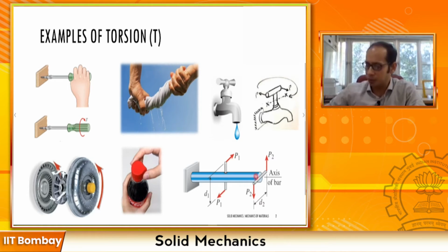And if you try to gauge the effect of this P1 and this P1, equal forces separated by a distance, as you can imagine very well, here your torque is going to be what? Torque is typically represented by this variable T over here. So for this one, your torque is going to be P1 times D1, right? And if I call the previous one T1, and I call this one maybe T2, T2 will be equal to P2 times D2 over here, right?